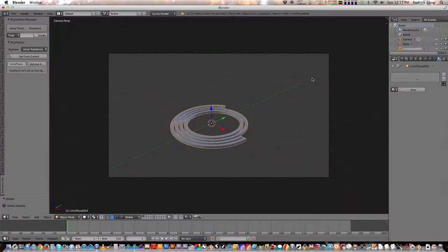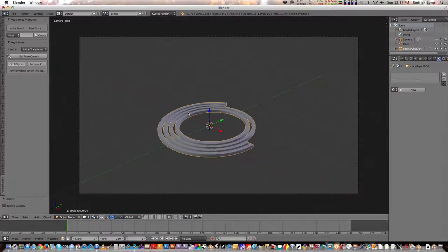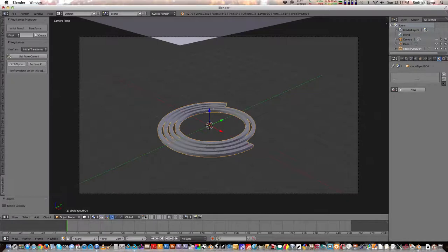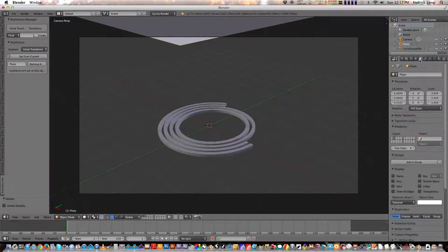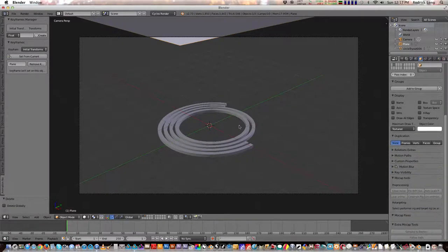Okay. And basically in Blender, all this area that's dark gray is outside the camera's view. The area right here is the camera view. So I'm going to bring that in. I'm going to make sure I activate my other layer. And there's one other thing I want to do with that light, because as you can see that little piece of it will show up in the scene if I don't take care of this. So I want to go over to ray visibility, uncheck camera. Now the light will be there.